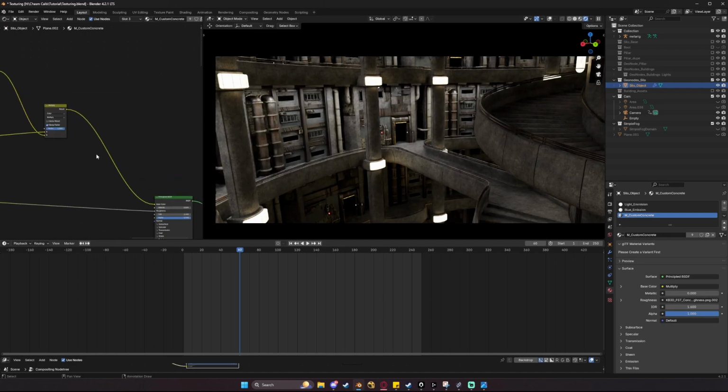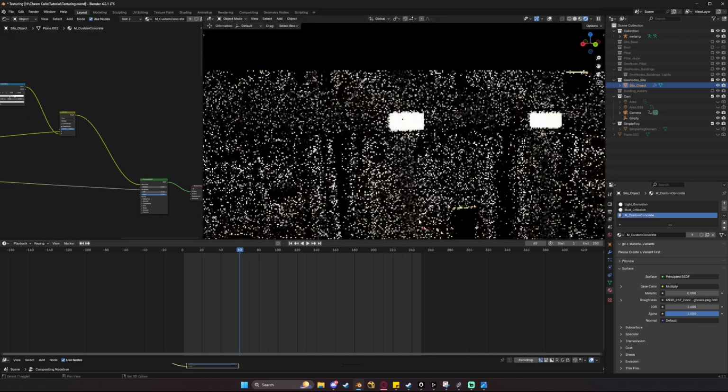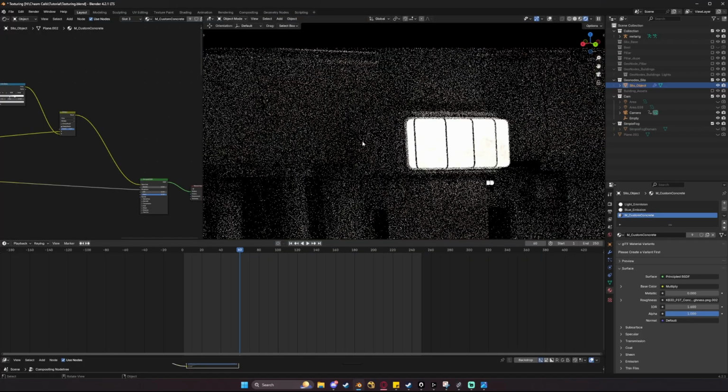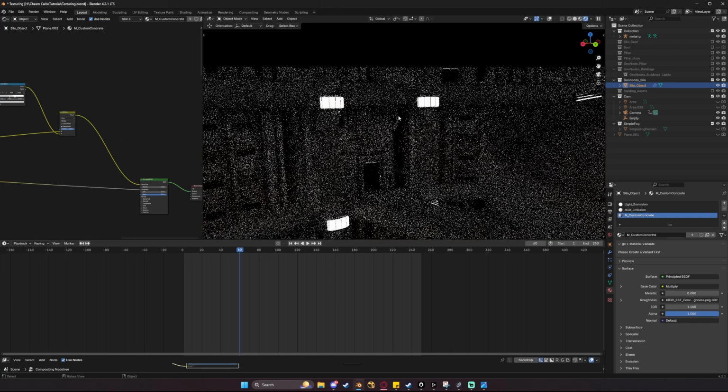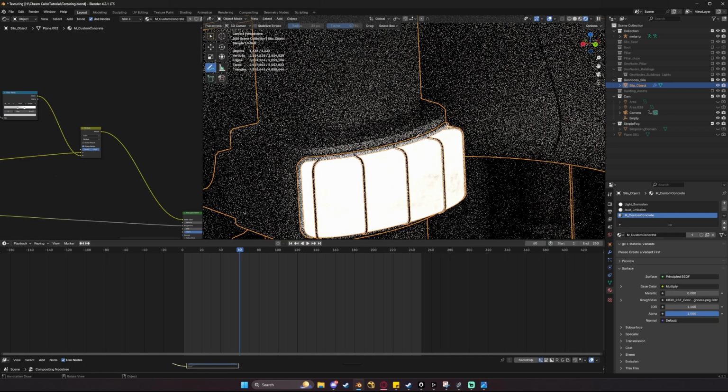So the next thing I want to do is add some ambient occlusion to this whole scene. Ambient occlusion essentially means that as one object is in proximity to another, it gets darker. In real life, you have a lot of natural ambient occlusion, and even here we do. We can see that due to the lighting over here and from the ground, we have this darker area behind the light source as things are being occluded. Of course, ambient occlusion also works to darken areas like this, where you would normally expect some dirt to build up in these little crevices or ledges that we see.